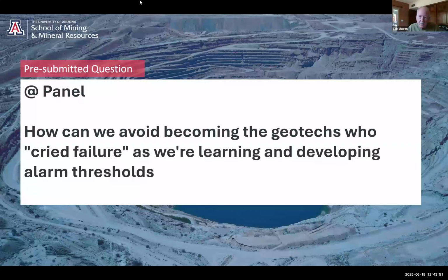Get your safety people. Safety people are probably the best ones to coordinate it. Run a test of your emergency response system, where you have a trial of a slope instability occurring. You've sectorized your pit so you know which part of it you need to close, and run a test of it. See how it works.